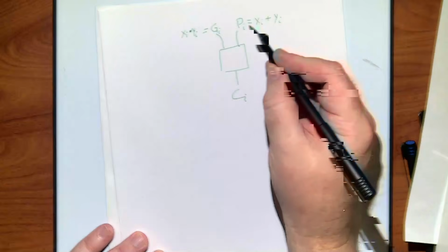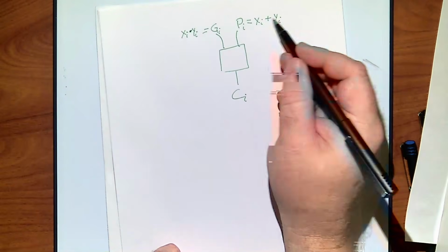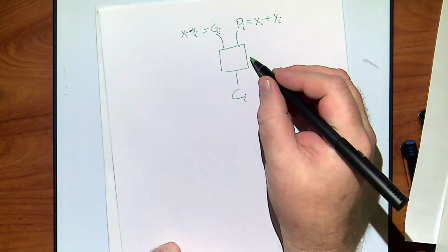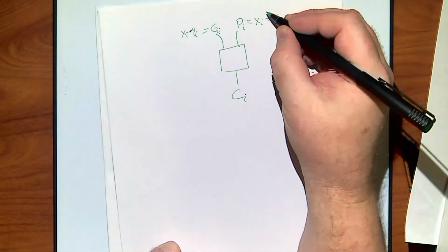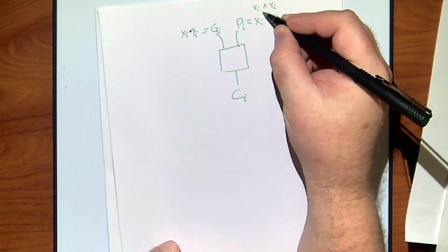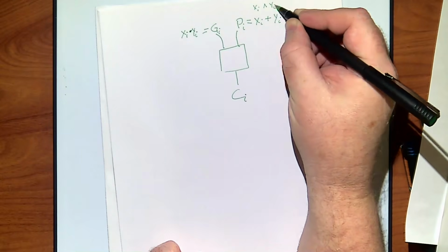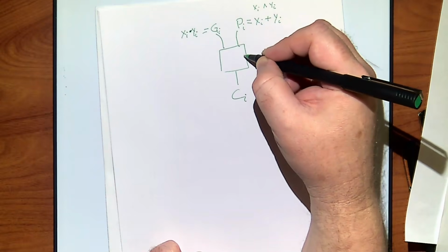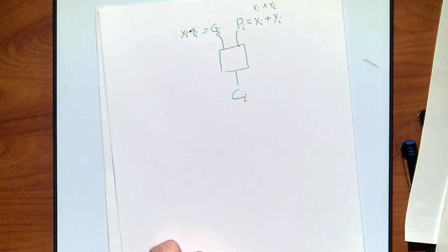It's technically x or y, because if they're both on, I still want to say something's happening. Although I will say the reason it doesn't matter is that if you put xi exclusive or yi, the propagate will be wrong in the case where they're both on and there was a carry. But if they're both on, it generated, so it doesn't matter, because generate takes that case for me.